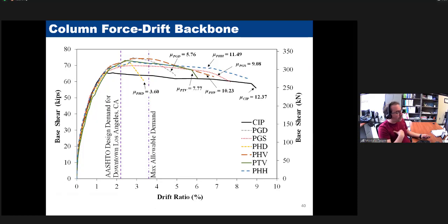And if you take a look at the current AASHTO requirements, all 6 precast columns that we tested met all the AASHTO requirements. I'm talking about maximum demand at the site, we are talking about downtown Los Angeles, minimum displacement capacity of 3. All of these columns met the requirement, so they are recommended for use in all 50 states. But again, PhD Dextra needs to improve the coupler behavior and make it a seismic coupler. If they do, this number will bump up to 5-6%. That's our expectation of this product.